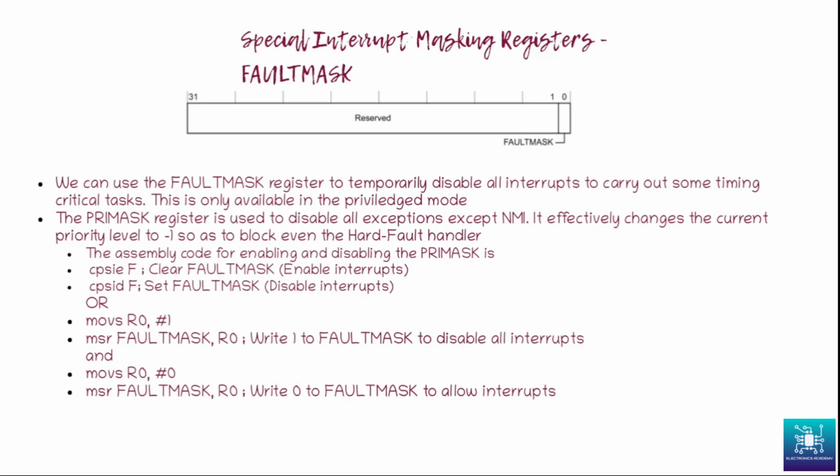If an interrupt service routine and a thread are sharing a particular resource, and you want a particular area of code to not be interrupted because it will cause certain error conditions where the shared resource may be overwritten by the interrupt and have a different value from the one expected, that is not desirable. So we generally disable the interrupts when we are in a critical section of the code.